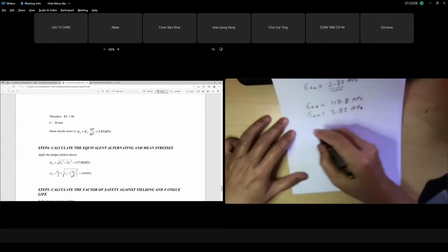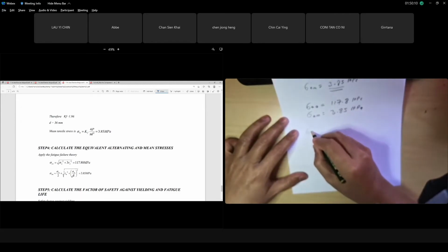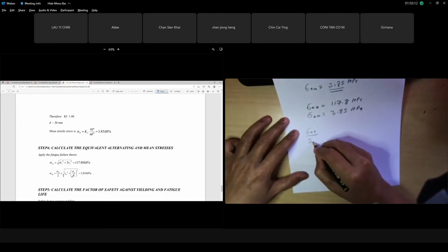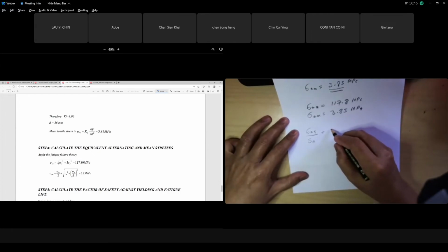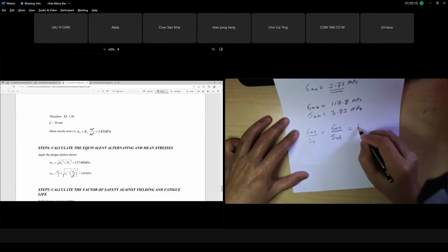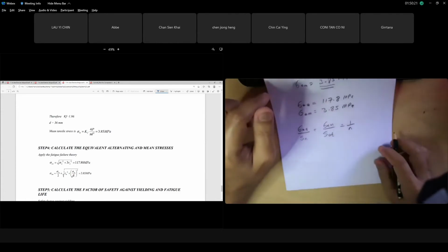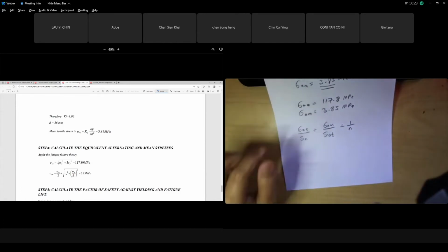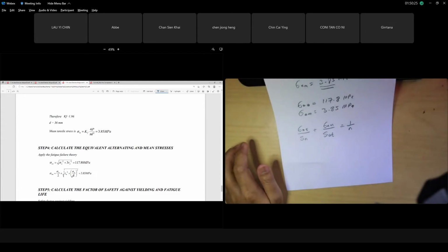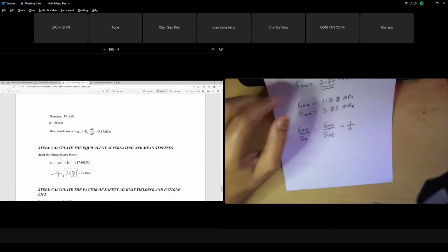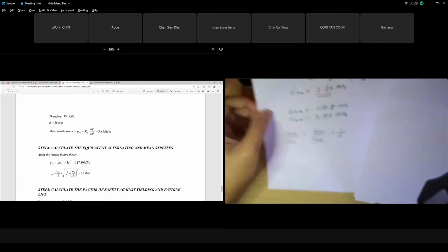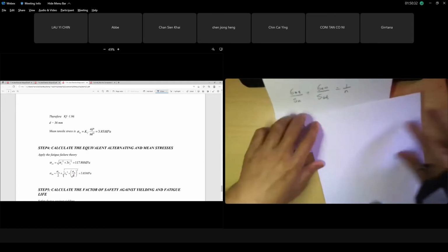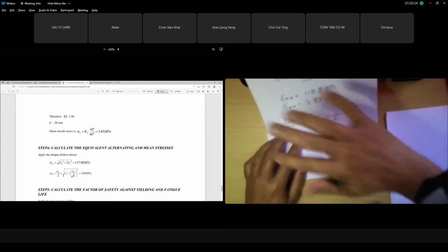So safety factor, okay, sigma EA over SN plus sigma EM over SUT equal to safety factor Goodman line lah. Okay, Goodman line. Okay, panjang juga cerita ni. Tak apalah, ini I hope you learn lah. Tapi kalau for your test tak ada this long lah, dia bagi you little bit simple lah, simpler. Okay, sigma EA already class, are you with me?